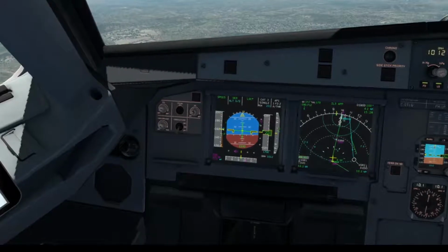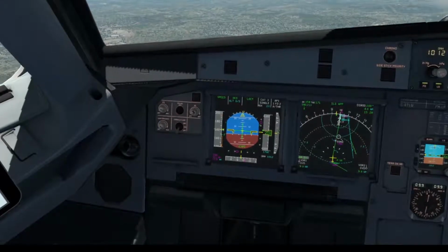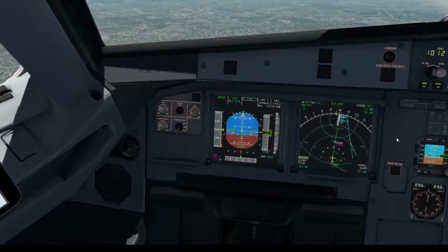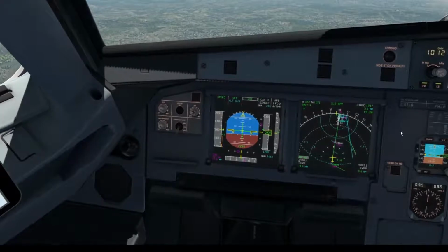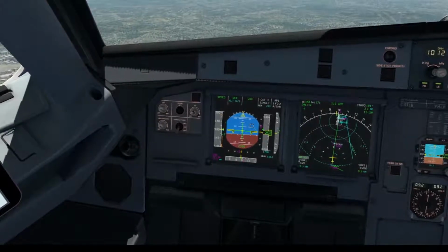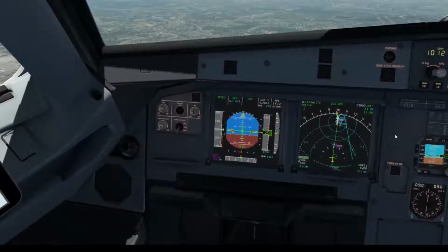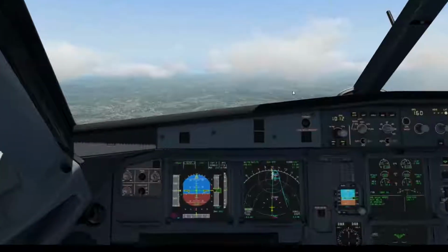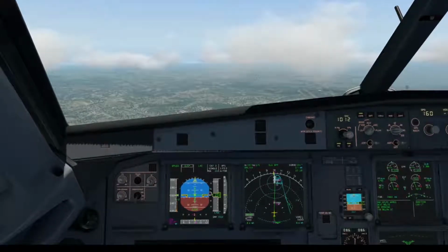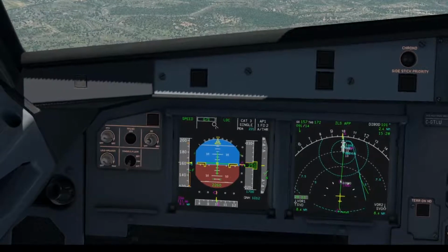And we've just passed the 10-mile ring, okay? So from here to the 4-mile ring, ATC will often tell you maintain speed 160. And that's what we're doing, 160, and not less. That's the important thing. So localizer is now not localizer star, it's captured localizer. Glide slope star. That means glide slope is coming in, as we can see on the dot here. The diamond, we're very close to it. Glide slope captured.